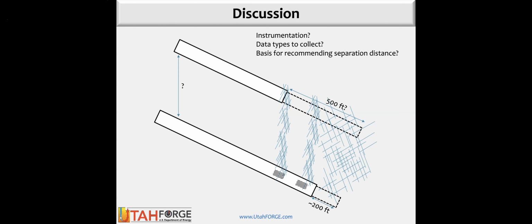What we did see is that the pressure signature from the open hole toe more closely matched our sensitivity case for a weak DFN, the native pressures, which would be more susceptible, so the DFN would be easier to stimulate. That's what the pressure history matched. For our perforated zones, our pressure more closely matched a narrower, tighter fracture growth.